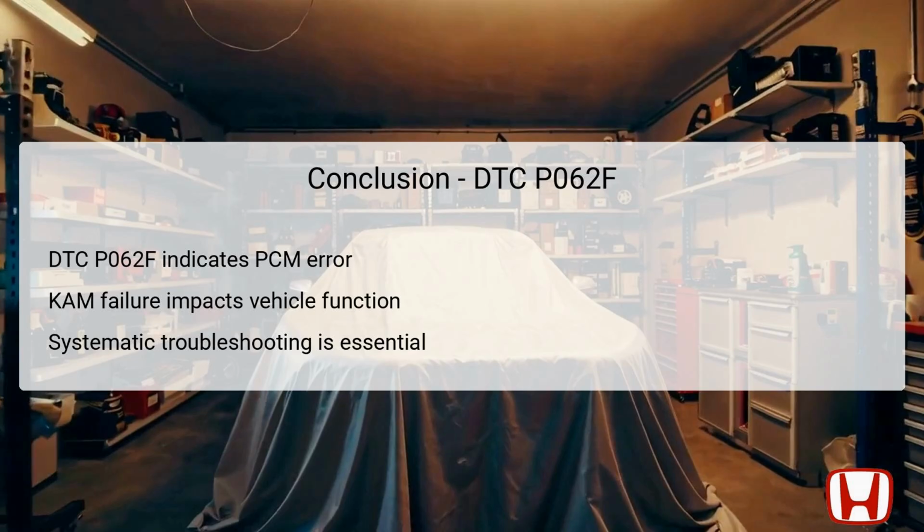The role of the PCM is paramount in managing engine functions, and any failure in retaining KAM can disrupt the overall vehicle performance. Systematic troubleshooting involving verifying the DTC, updating the PCM, or substituting with known good parts is essential for accurately diagnosing and repairing this issue.